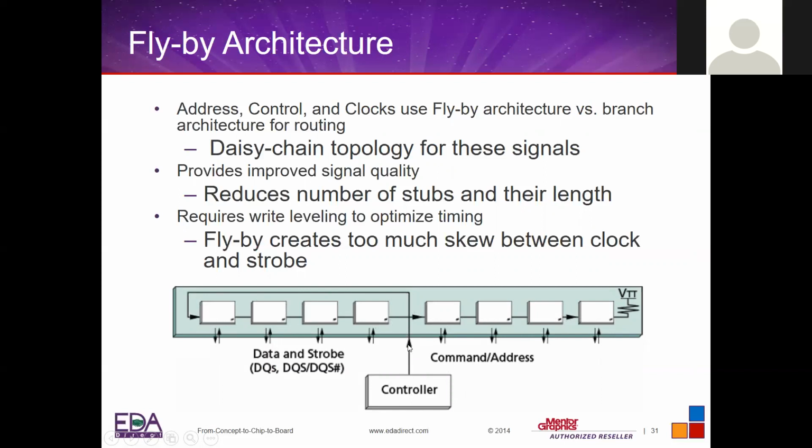On the DIMM, on the board, you might choose to use a T topology to distribute 4 and 4. So which one's better for me? And then the termination is at the end. So, things get difficult pretty quickly. Which way is best for me?